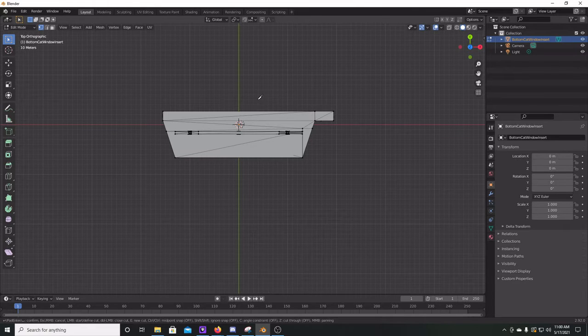And hit K for knife. Now if you just go ahead and do it now, you could just make this all wobbly line and that just won't work. Then if you hit Z, it'll make the line straight, but it'll just be like all over the place. You can make it straight, but it'll be hard to get it just right. So if you hit K, Z, and C, the K brings up the knife, the Z makes a straight line, and the C locks it to an angle, like so. Then just right click, and then hit enter.